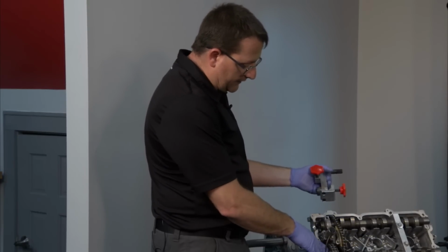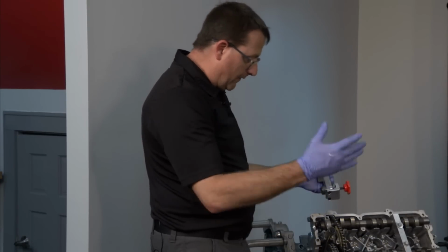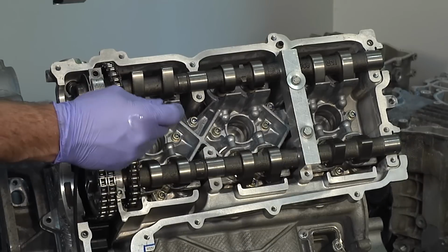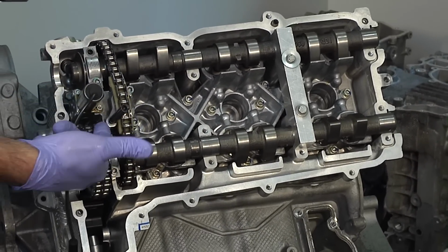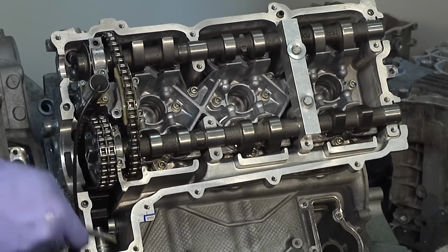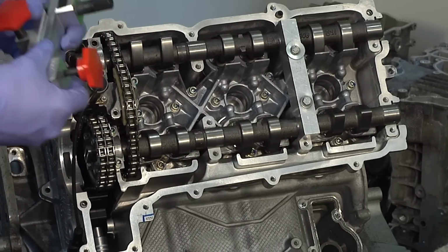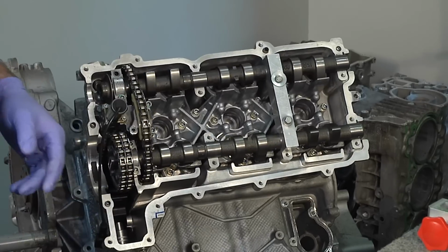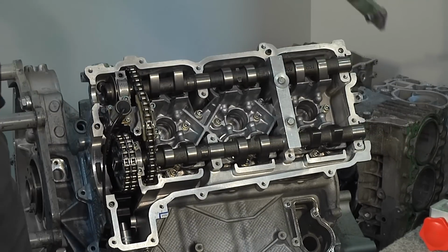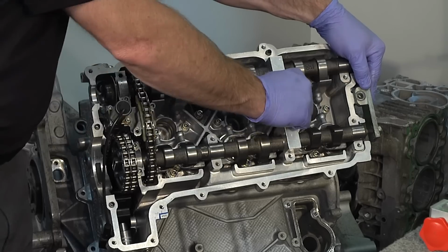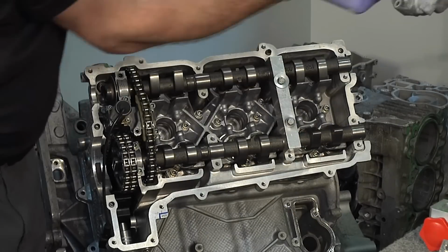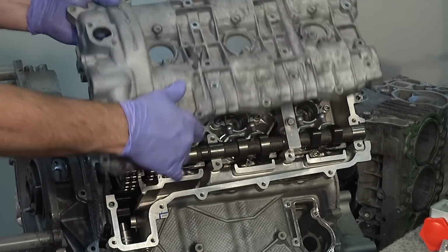And we're going to put on the exhaust cam sprocket and all that sort of thing, and we're going to use our special tool like this one, and we're going to release the load from that tensioner unit. Once that is done, the camshaft timing can then be set correctly. We're going to put this bridge back on the rear, remove this bridge, and then we're going to end up putting the camshaft cover back on.